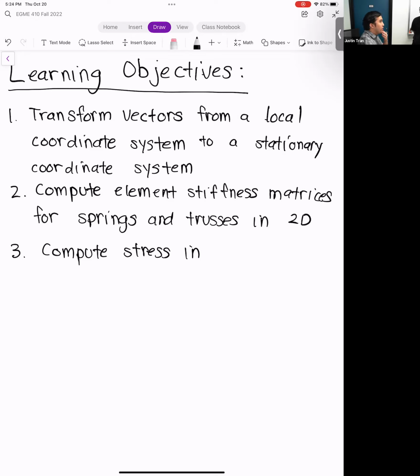I'd have to do a little more exploration in ANSYS in terms of how you can do that, but you can do a radiation boundary condition as well. What I would probably do is input the temperature of the engine into a radiation boundary condition. Then you would need some way of finding the emissivity of the surface. Do you remember we went over that in 4.7? Maybe the tape has the emissivity listed in its properties, and you can put that into ANSYS. But the emissivity of the tape is key to the calculations.